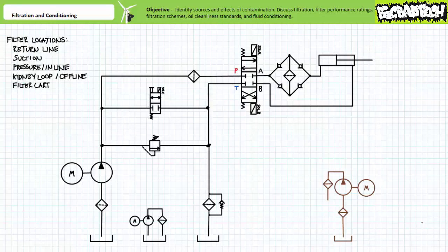An example might be some stuck-up hoity-toity valve that has no fondness for the dirty oil enjoyed by the rest of the common rabble. Ordinarily filters are meant to be unidirectional, since running a filter in reverse would blow out any previously entrapped contaminants and run counter to its intended purpose of cleaning the oil. This pressure or inline filter on the pressure line leading to the directional control valve would be unidirectional. Pressure or inline filters installed in bidirectional flow paths ordinarily use an arrangement of check valves such that incoming fluid is always routed in to out as intended regardless of direction of flow.